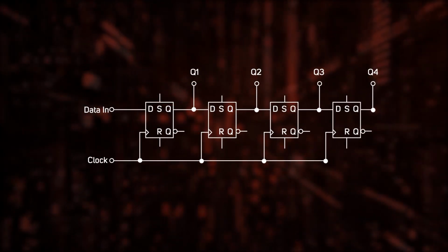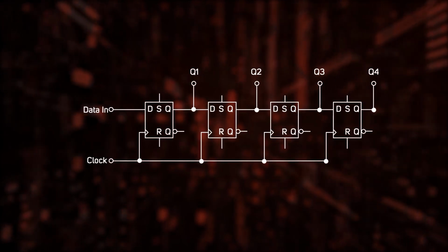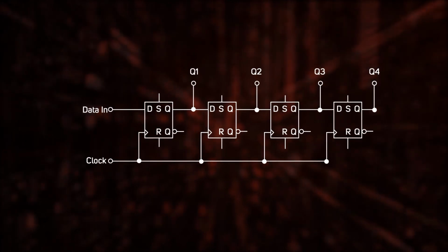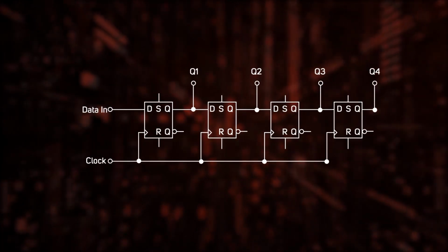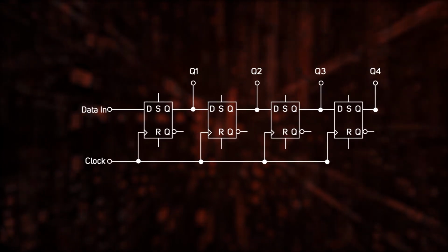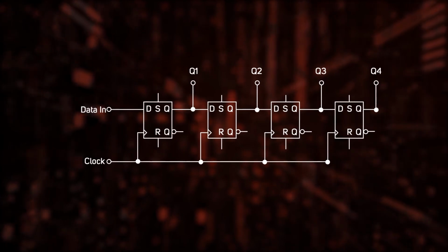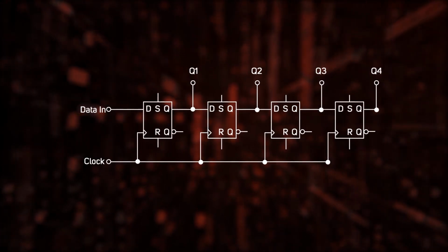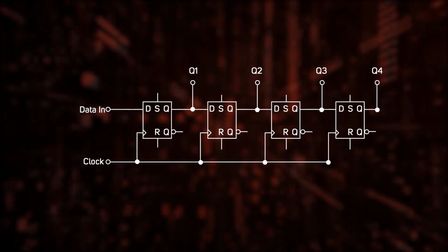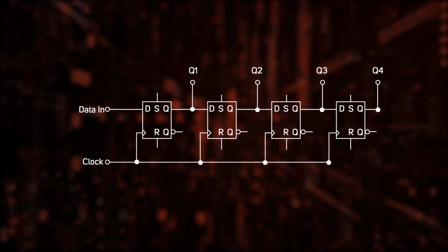Next, the second rising edge of the clock has come. Now, the external input will feed 1 into the flip-flop 1 and it will reset its previous value. The second flip-flop will have a 0 inside it now, which got transferred from the first flip-flop. Simultaneously, the output at Q2 will also display the value which is stored by the second flip-flop. So, at this stage your 2 bits of external inputs are set.